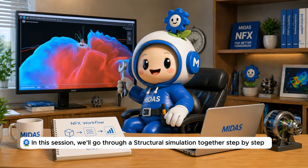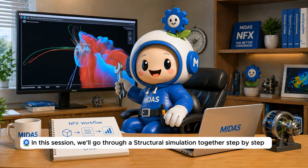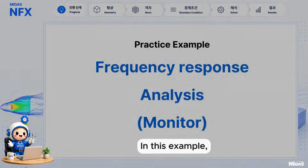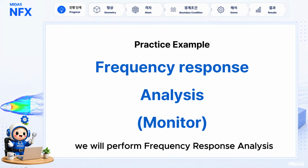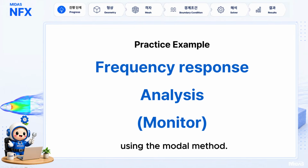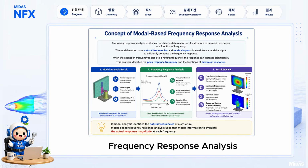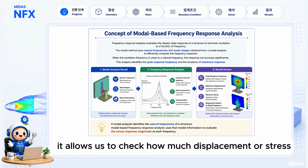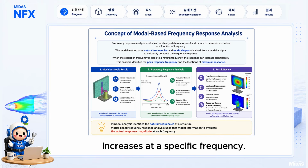In this session, we'll go through a structural simulation together step by step and follow along with the practice example. In this example, we will perform frequency response analysis using the modal method. Frequency response analysis evaluates how a structure responds to repeated vibration excitation at different excitation frequencies. In other words, it allows us to check how much displacement or stress increases at a specific frequency.